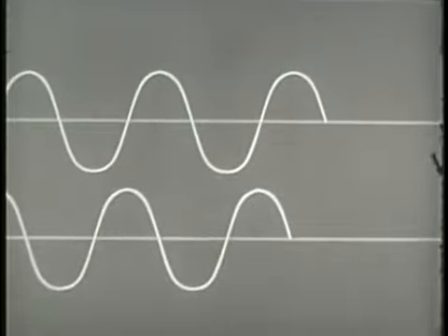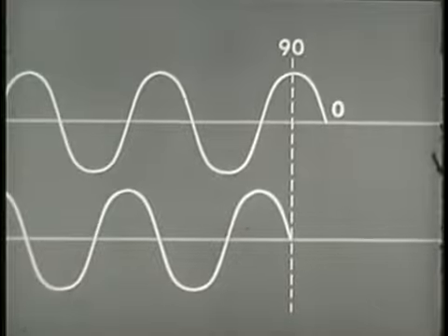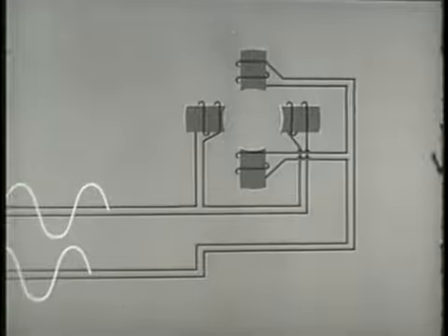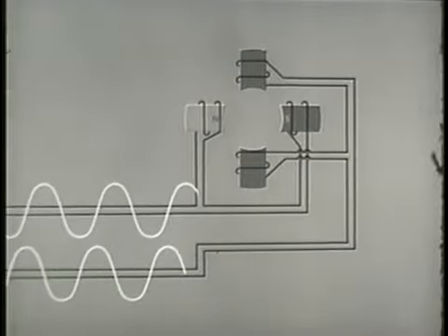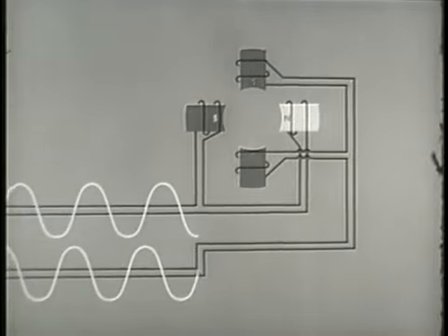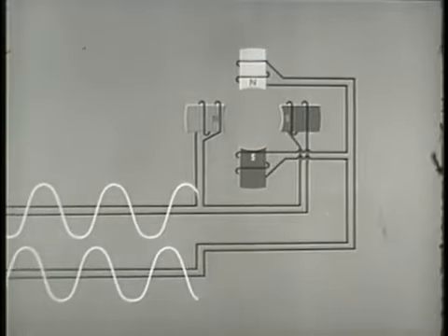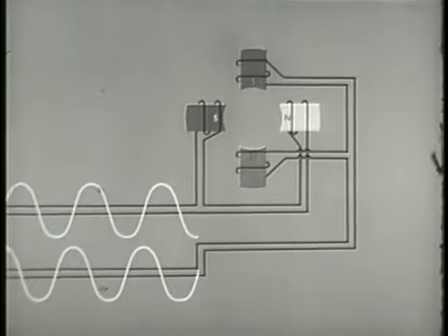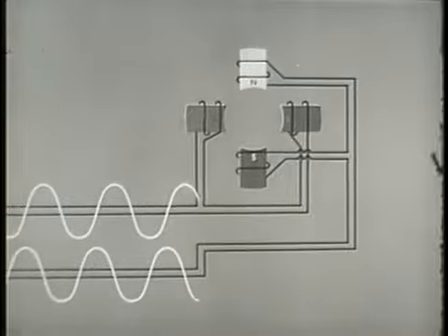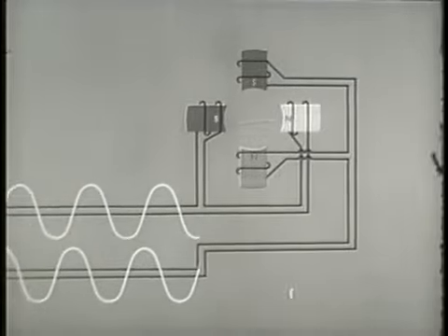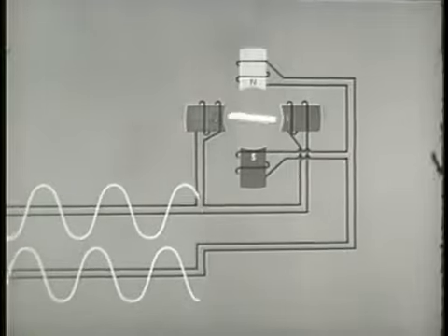The current used in this motor is two-phase AC. That is to say, two separate AC voltages 90 degrees out of phase. Just as in three-phase motors, the phase difference is used here to energize the field poles progressively, thus causing electrical rotation of the magnetic field. As in all induction motors, electrical rotation of the magnetic field is a primary objective. Again, the rotor turns in the same direction as the magnetic field, but at a slightly slower speed.